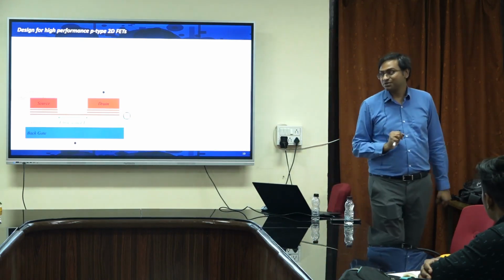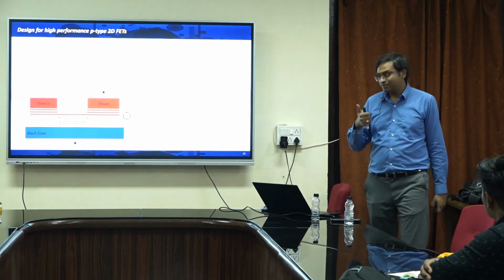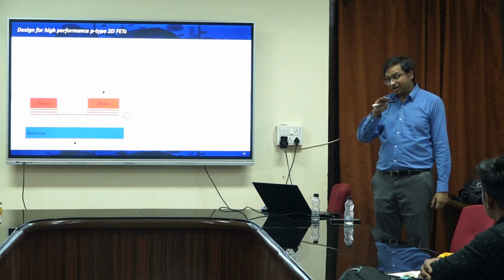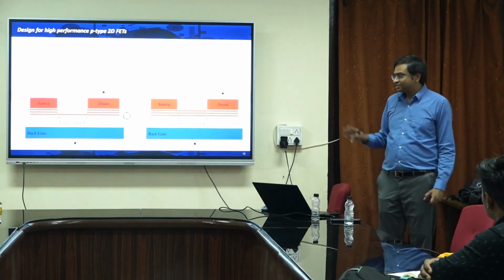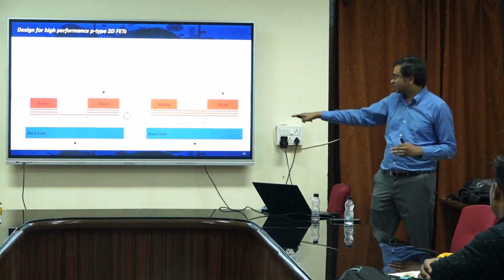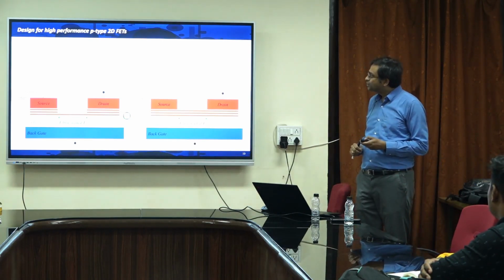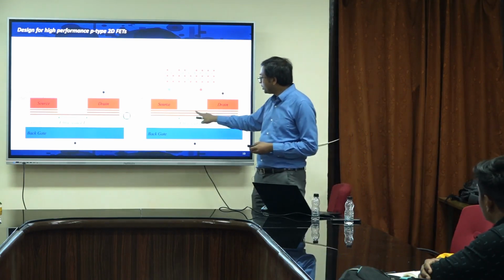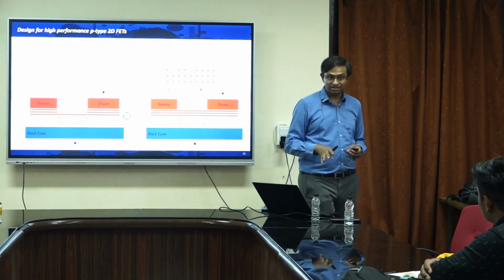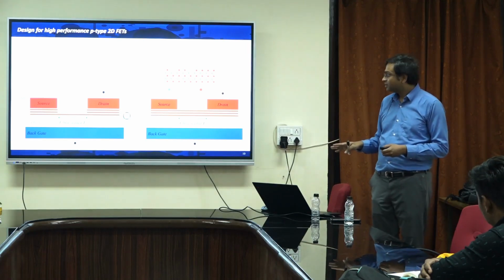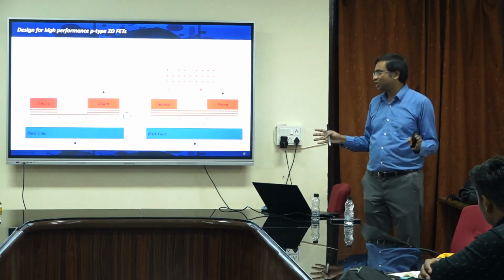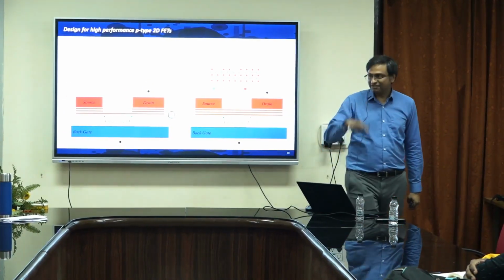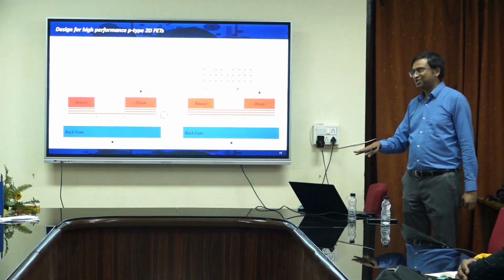This is where 2D materials come to rescue. An amazing property of the 2D material allows us to do something called atomic layer etching. You can etch layer by layer. So what we do is, we start with these multi-layer flakes. All 3 layers are there. Oxygen plasma converts only the top layer into tungsten oxide or moly oxide, and it stops there. You can keep doing the plasma for long, it will not affect the layers below. It's a self-limiting oxidation process.